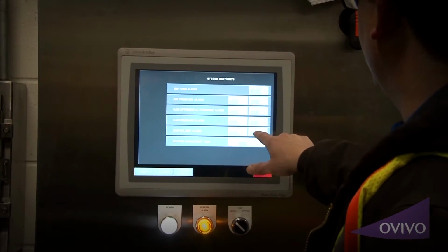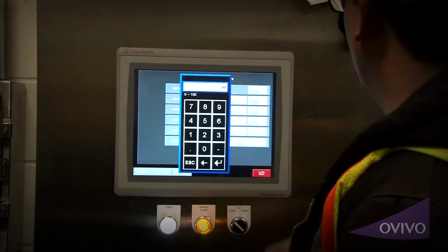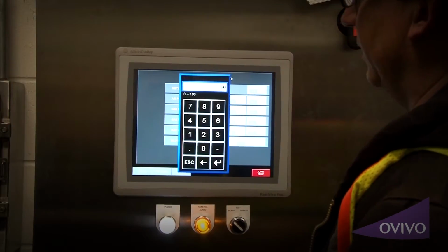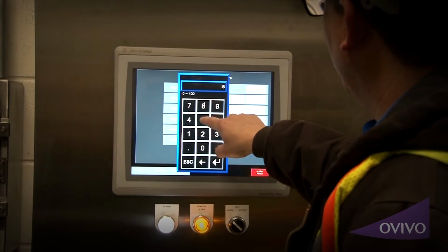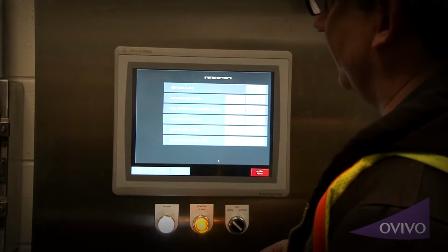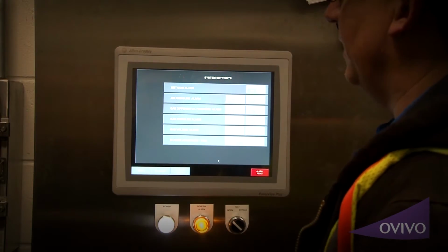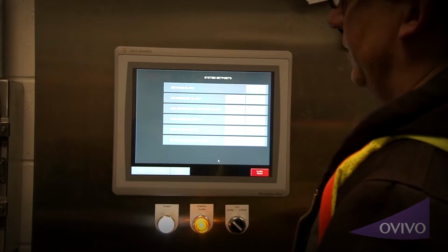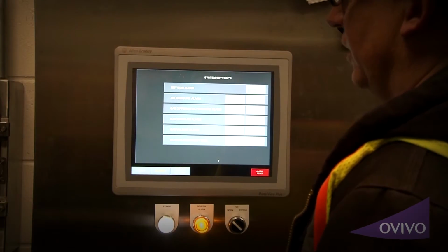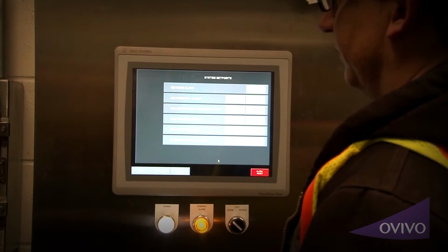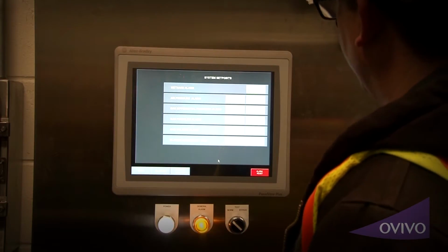And if you thought 10% wasn't enough, and you were going to go home for the night, and you didn't want to worry about an alarm, you could set this at 85 earlier in the day, and if it ever hit 85, take her down to at least 85, and then you know you have enough room to operate till the morning time. You can manually turn on a flare, or you can hit the boilers hard, or you can do whatever you got to do to get some of that stuff out of there.